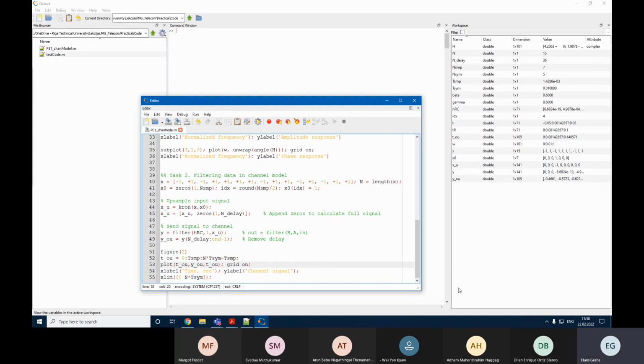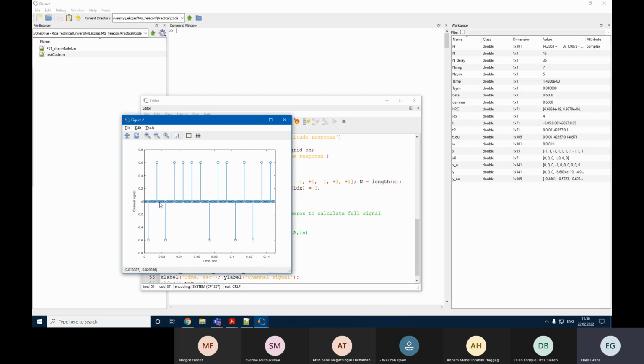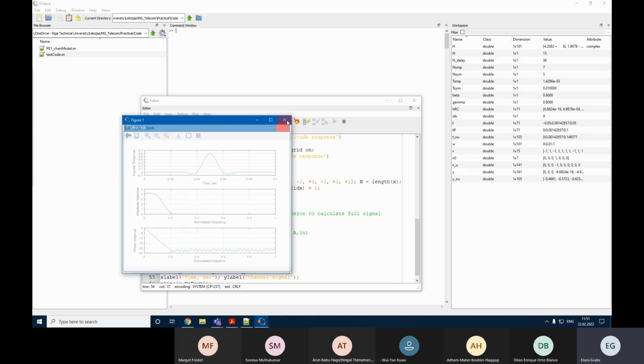So I remove this and I will use it like this way. If I use stem here, and that would be t out, by the way, I didn't remove it, then it will just overwrite my existing plot. So let's see how it works. Yes, I have plotted one plot and then the second one just overwrites and that previous blue line removed. Yes, it's not what I want to happen.